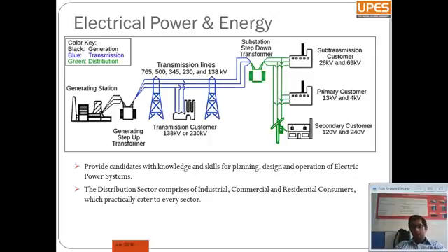As you are aware of the basic Ohm's law, we also have the power conservation. If we step up the voltage, the current reduces. As soon as current reduces, the losses go very low. So the longer the transmission lines, we increase the voltage levels for each transmission line. That's how we are basically transmitting power from one end to the other.